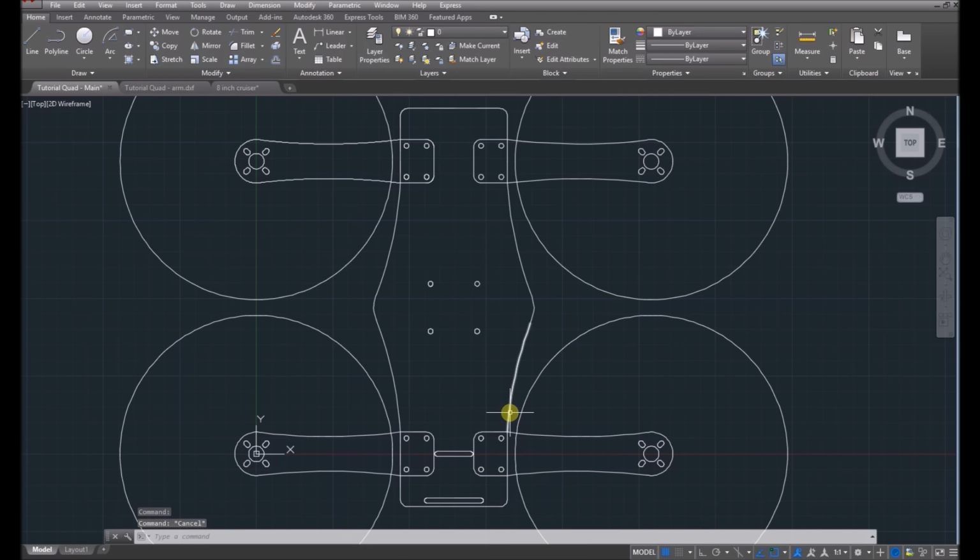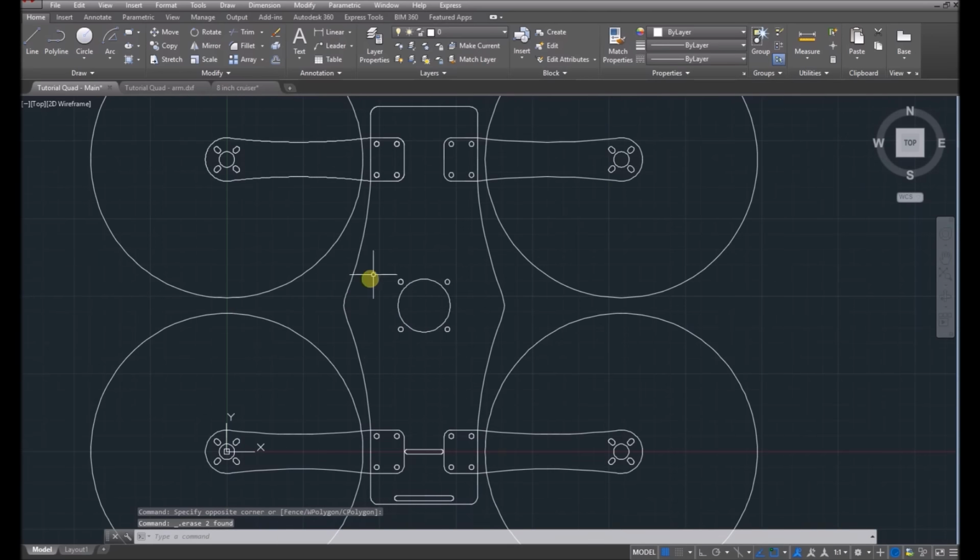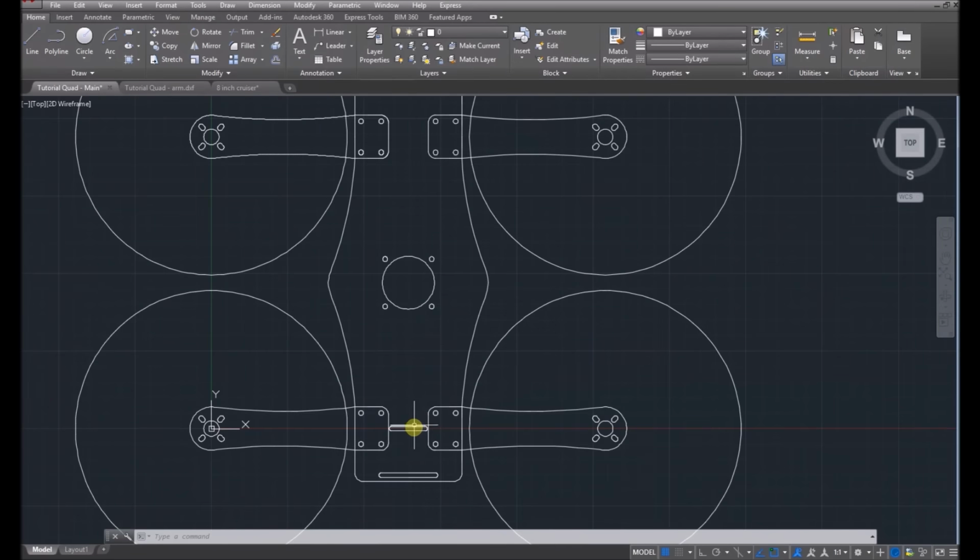But let's assume for this one we're going to get 2 pieces cut out exactly the same, just like a ZMR frame, for example. What I'm going to do here is just mark the middle, and then I'm going to draw a big circle, because let's go 17. Because of the way this is designed, it seems to me like we could cut out a lot of the middle and still keep a lot of strength. You can get more intricate with your cutouts. You can draw different shapes.